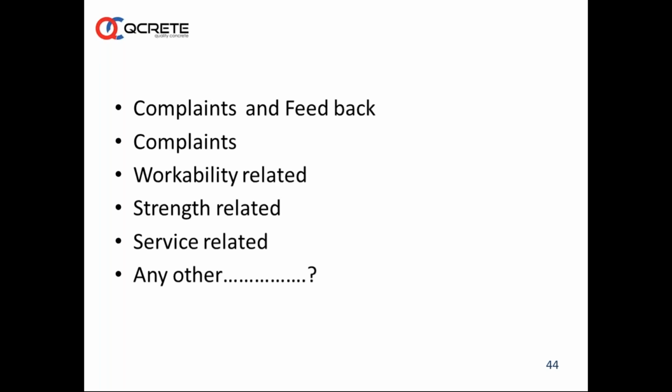So delivering exact slump after traveling for a distance of 2 hours, or in traffic situations, 1.5 hours in, let us say, in metros, if the truck travels for 1.5 hours or 2 hours, exact slump delivering is not easy actually. I'm not telling it is impossible. What I'm trying to tell is it is not easy actually. Okay, so we need to understand this particular point.